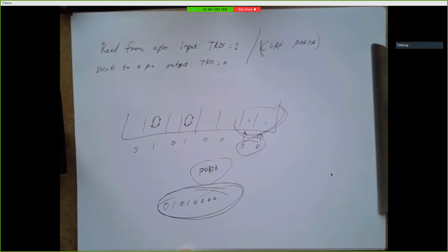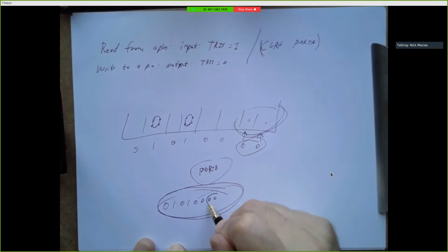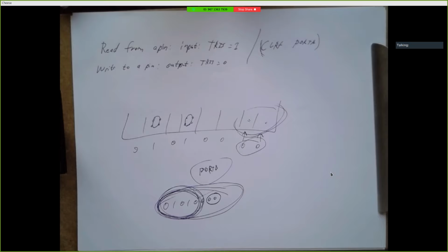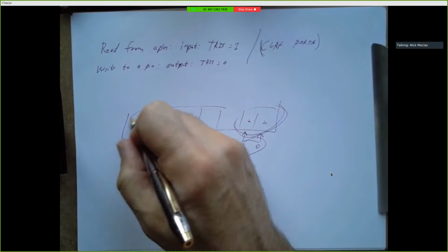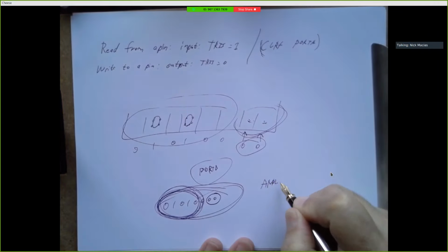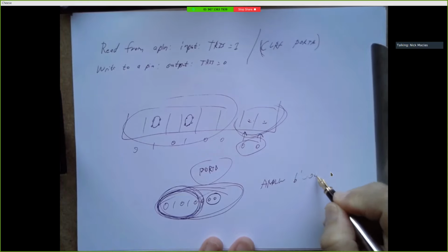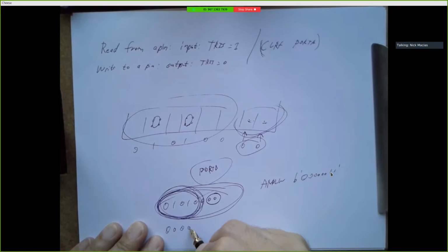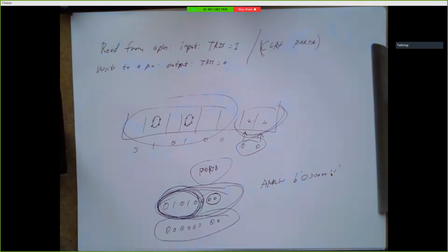That doesn't work, because when I read from port B, I have information telling me if those two spots are empty, but I have all of this other stuff in there too. And if you read from port B and then try to treat that as a 2-bit number, 2 of your bits are correct, but your other 6 bits, who knows? Probably not correct. So the third part of this question was to mask off some of your bits. In other words, do an AND. If this is in the W register, you can AND it with the literal consisting of 6 zeros and 2 ones. And that's going to force these upper bits to be zeros. And now my W-reg would look like that.